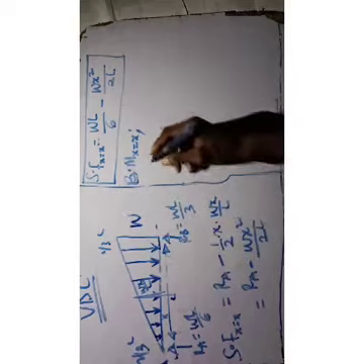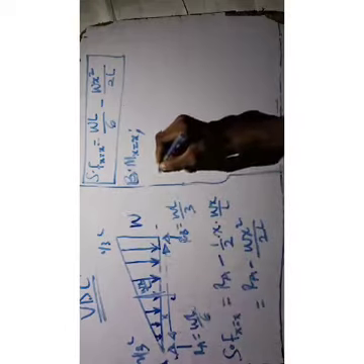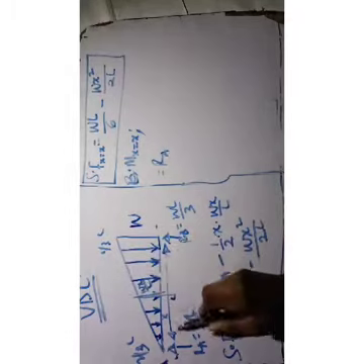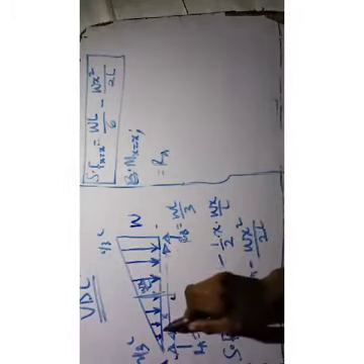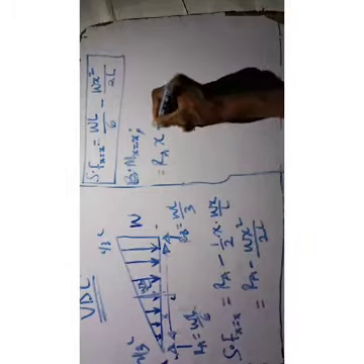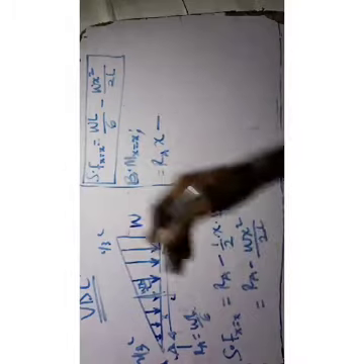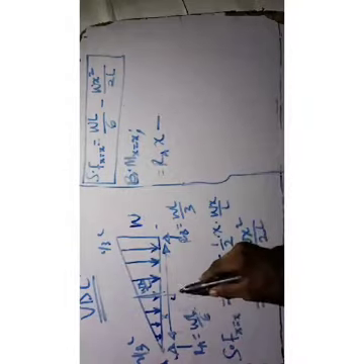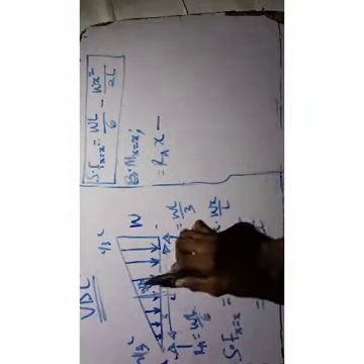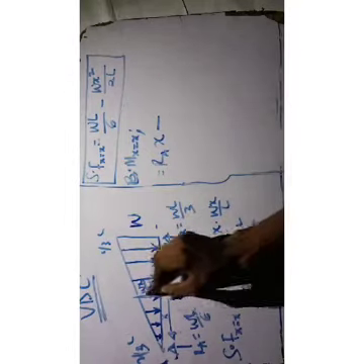So that will be RA times the length it covers. Let's say at any section, that will be RA times the length it covered. Let's say X. RAX, right? Minus, that is clockwise minus anti-clockwise. So clockwise minus anti-clockwise will be RAX minus, at any section, we know it as WX over L, and that is the height.